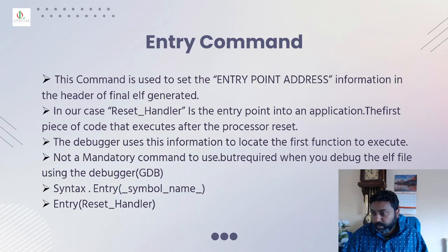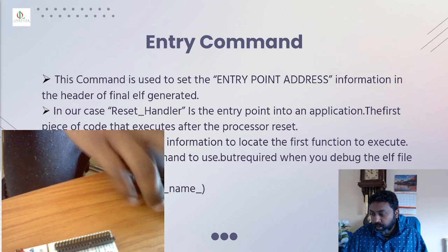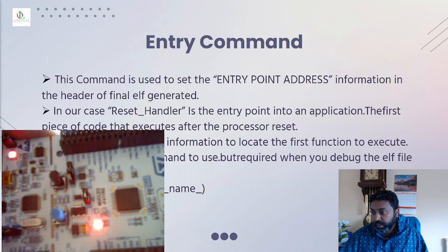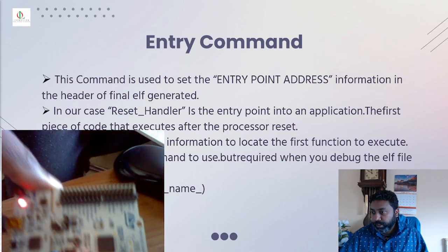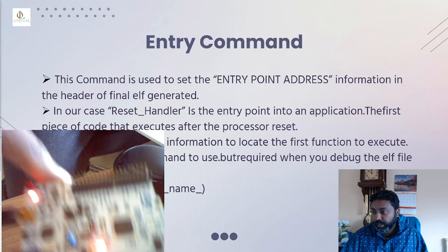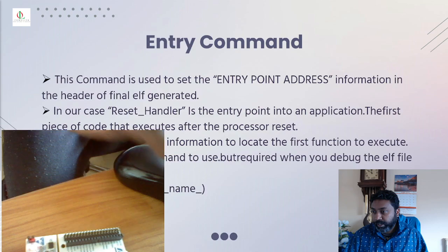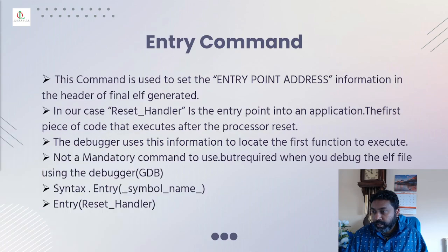So the entry command is nothing but once you press the reset. I just connected my board. I'll show you. I have connected my board, as you can see. It's connected to my computer, so that's where I generated the LD files, the linker description files. I went ahead and did the build project.